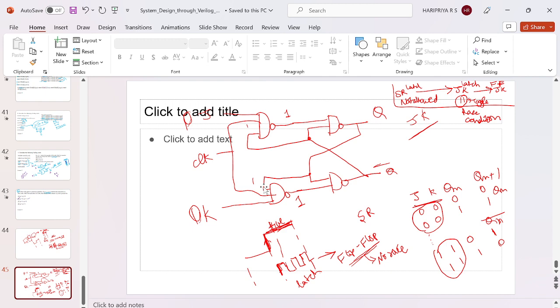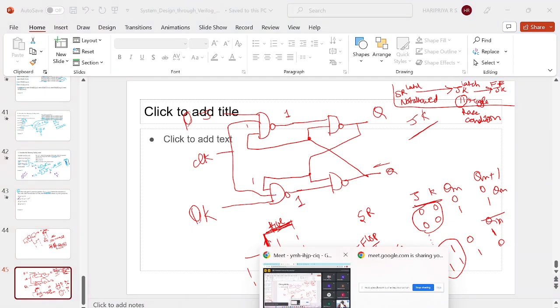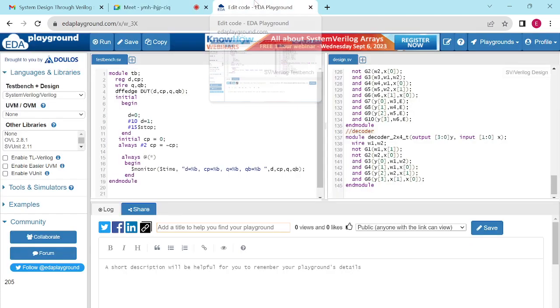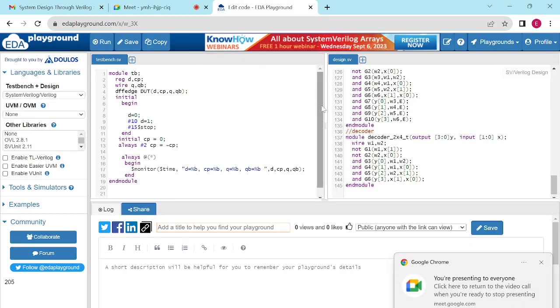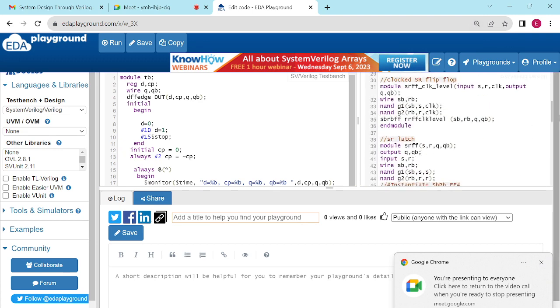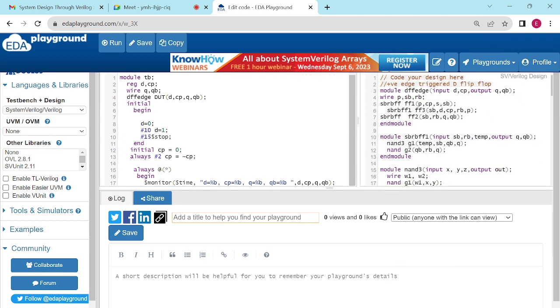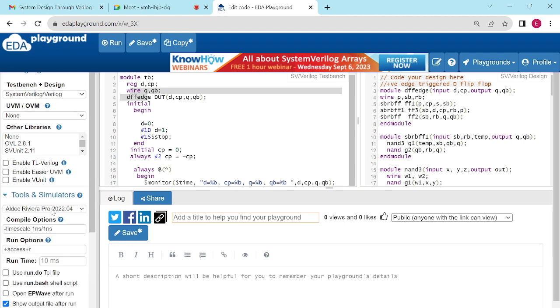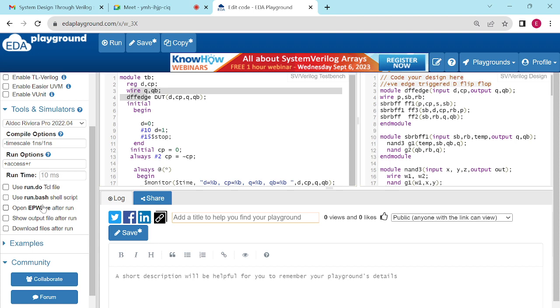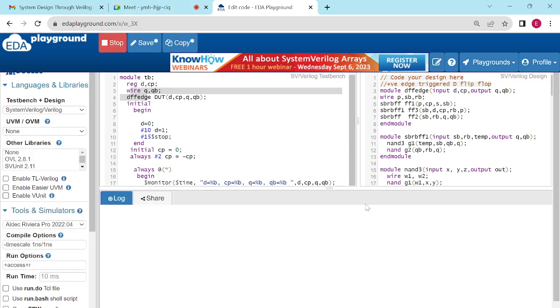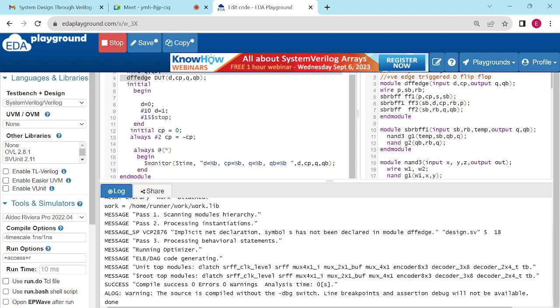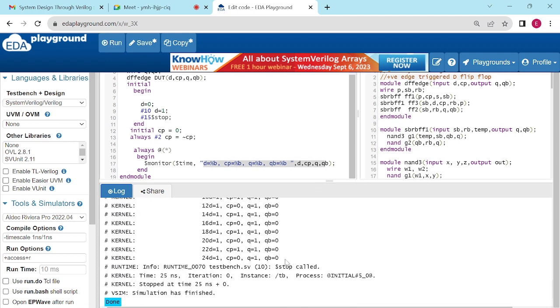Okay, the first question is where to test this Verilog code. In the previous lectures, in the previous week, maybe you have seen, this is the EDA Playground, where we can simulate this Verilog code. This is an online and free platform. Here you go to tools, you can set any one tool, and if you want a waveform, you can set EPWave. I have given $monitor, everything I have displayed, so you will be able to see the final output here.